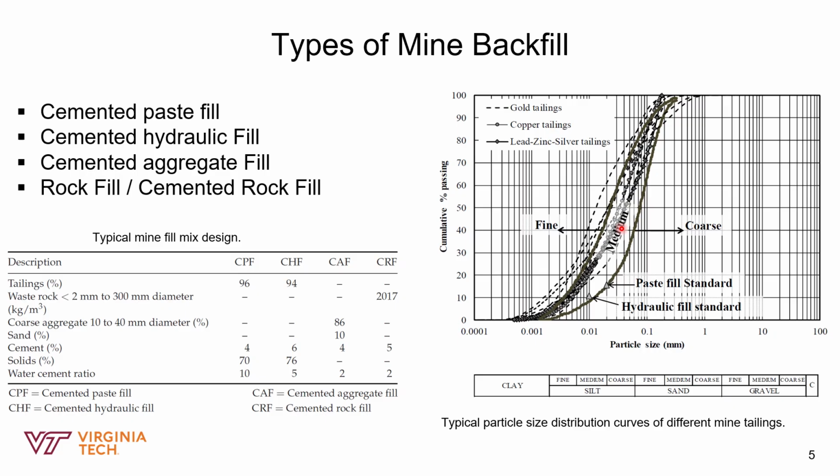And if the PSD falls in the fines region, it means that it is not suitable for hydraulic fill and it requires desliming for it to be used as paste fill.